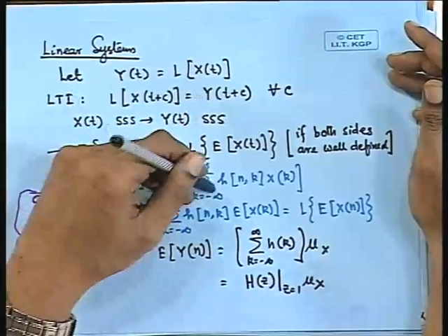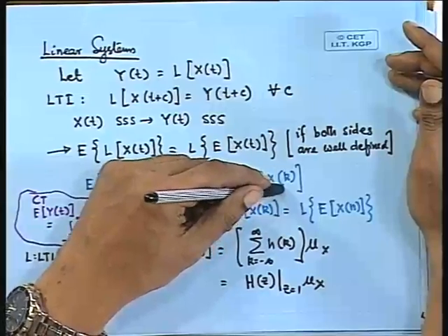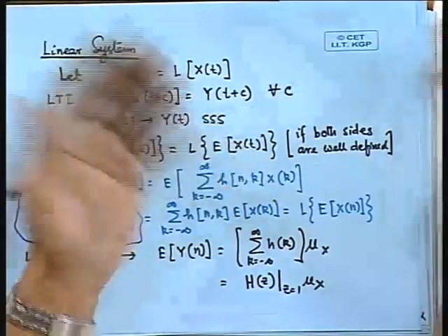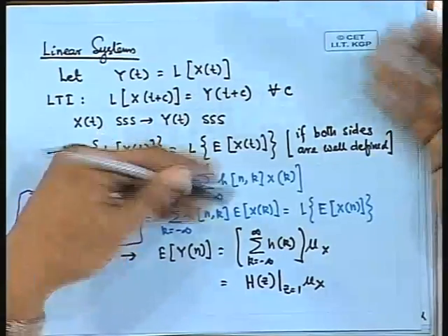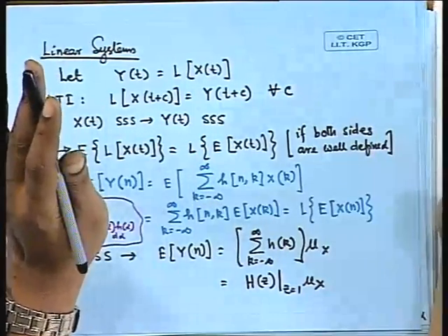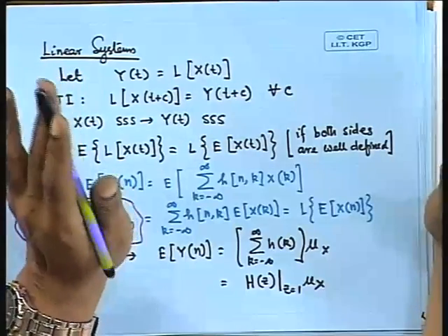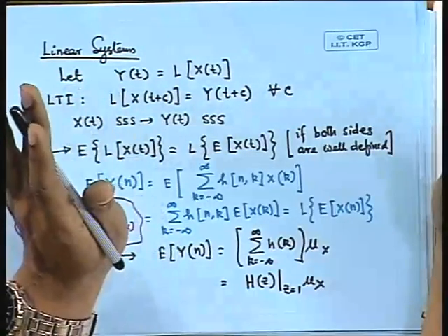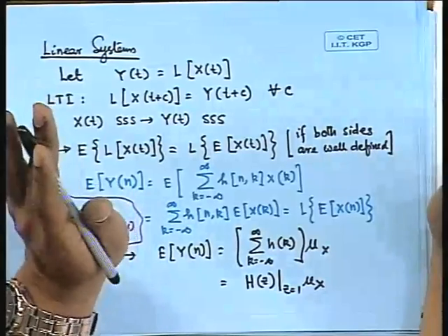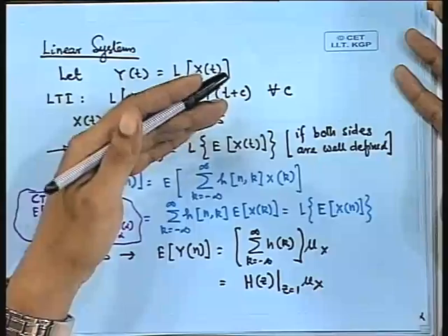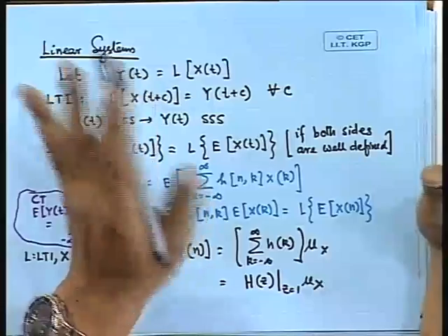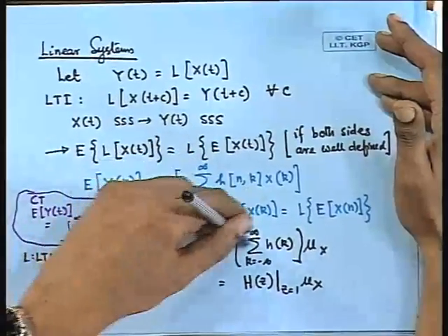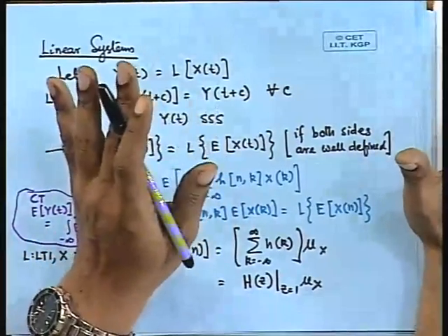So what you are going to do is you are going to sum this xk every time. Now xk is non-zero and you are summing it over an infinite number of terms, so that limit will not exist at all, right. So such complexities may exist, but for the time being we'll keep our eyes shut on that and only talk about BIBO stable systems, for which the impulse response sequence will be convergent, that is, the sum will actually converge. So we will only talk about those systems for the time being.